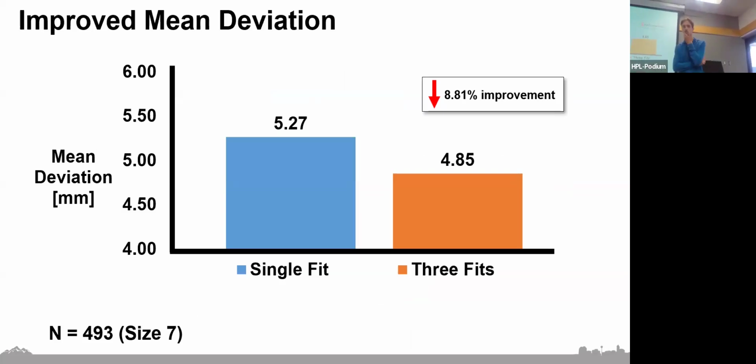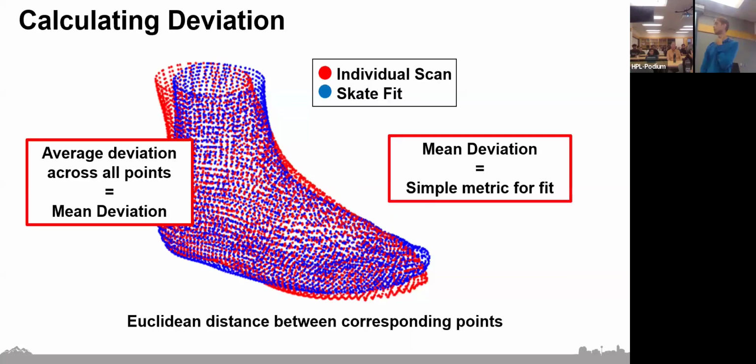So you calculate the deviation at the various points and then you calculate the mean. Yes, exactly. So if you can imagine, if point 0.1 on each scan is big toe, and 0.1 here is on blue, and then 0.1 is here on red, calculate the 3D distance. So imagine a vector from one to the other in 3D space, and calculate the length of that vector.